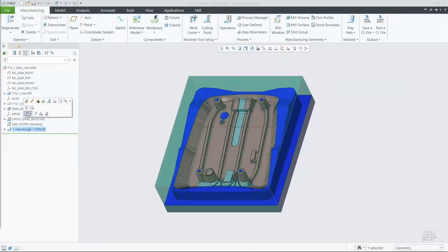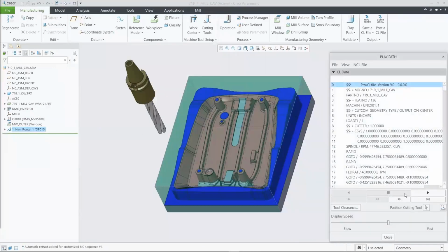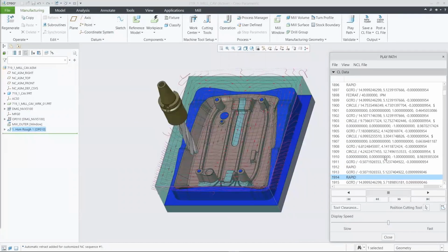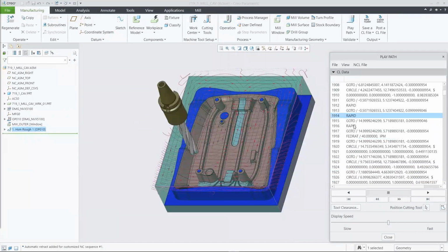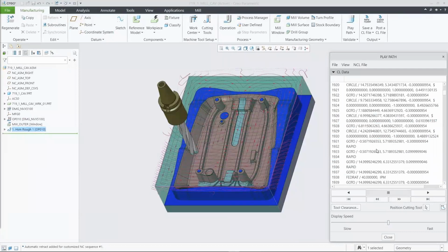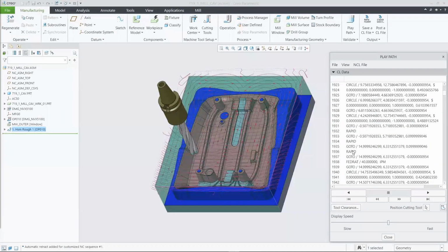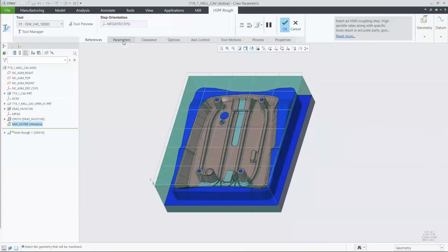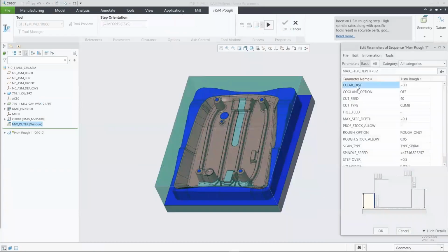You see that there. But like in most sequences that we have in the past, what we have is a feed rate step. And this is normally a constant that stays the same throughout the process, but depending on the complexity of the part that you're working with or the options that you've chosen, that could be a problem, right? So this has been a highly requested option that we've added in now to do adaptive feed rate control. All you have to do is within our parameters options here is switch a parameter for our feed rate.